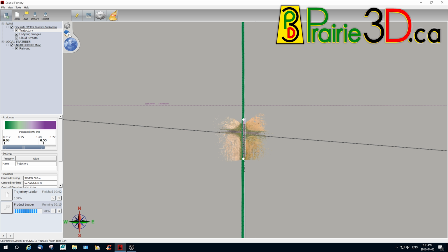I'm going to measure the power line here like I was talking about before. If you look off to the left side of the screen, after I do this, you can see a couple of points come up. There's an easting, a northing, and an elevation. So each of those points that I just measured has an easting, a northing, and an elevation. So you can see the difference in all of those. You can see the height. You can see how far west you go.